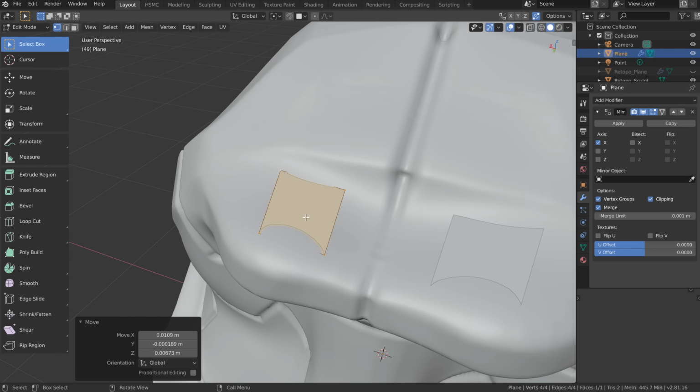Now one other thing is, I'd like snapping to be on all the time. So rather than toggling it with the Control key, in this case, I think it's just going to be better to enable that in the header there.